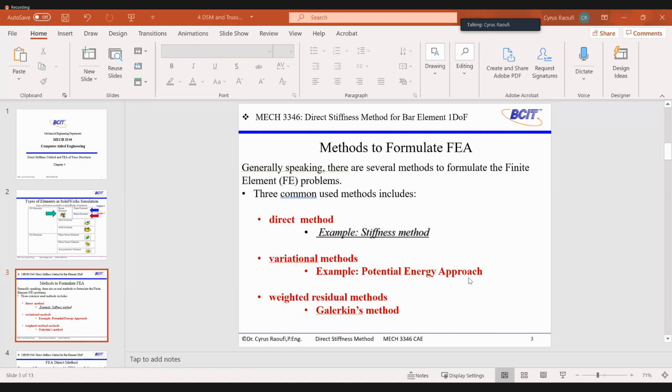And then there is a change of energy here. You are applying force that creates the displacement or deflection in the structure. That force multiplied by that deflection creates work, and work is going to be saved inside the structure like energy. Then you have two types of energy. You're applying the force as a work, and you can save the force inside the structure as a deflection. And we call that one potential energy approach.